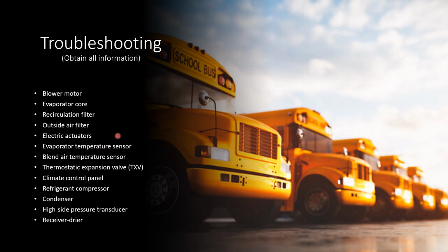What does the evaporator temperature sensor do? Obviously, it's a sensor, so it's going to send information to a computer, and you've got to understand how it works. Is it a 5-volt reference? Is it a 12-volt reference? You just got to understand how each one of these components works before you can start diagnosing, before you can start figuring out what's wrong with the system. This is also going to point you in the right direction if you understand how these systems work.